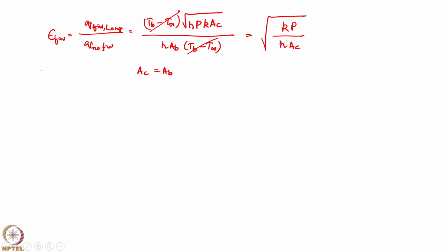Okay. So, that means this is having very important implication, we need to understand this. You want to increase effectiveness of the fin as high as possible. That is possible if you take very high conductive material, that is copper is better than aluminum, which is better than stainless steel, which is better than any plastic. Plastic effectiveness will be less than 1.